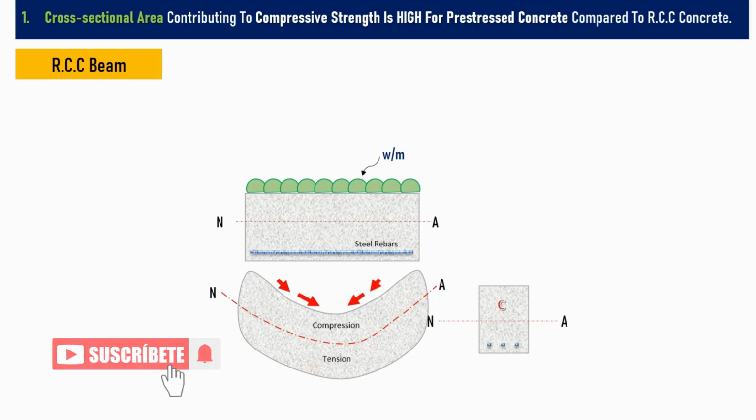This is concluded based on the real effects of load on the beam, where the top fibers contract and the bottom fibers expand. As the bottom portion is subjected to more tension, and concrete we know is weak in tension, we introduce steel reinforcement in this area. So to summarize, the top portion of the cross-section of the RCC beam only contributes to the compression strength, C. The lower portion is only for tension, T. The purpose of concrete below the neutral axis is mainly to hold the rebars upright in the layout.